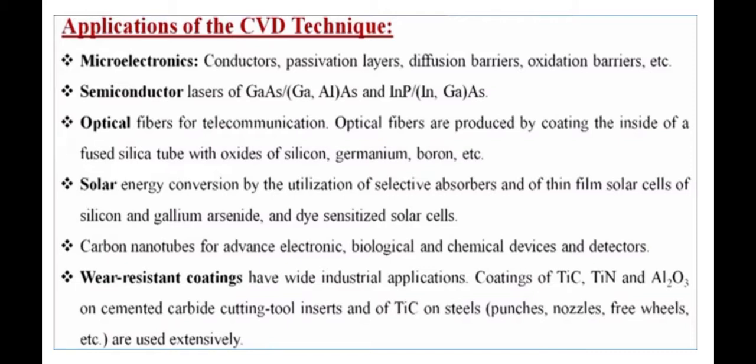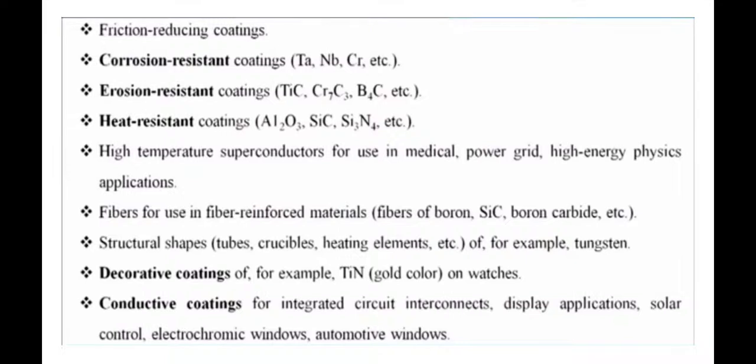Then wear resistance coatings have a wide industry application, coating of titanium carbide, titanium nitride, aluminum oxide on cemented carbide cutting tool inserts or titanium carbide on steel punches, nozzles, spray wheels, etc. are used extensively. Then friction reducing coating, corrosion resistant coating like niobium, chromium, etc.